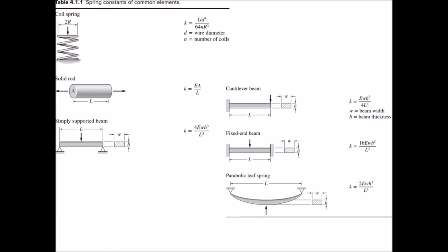So now that we've done this the longhand way, where maybe we didn't know this was readily available to us, or maybe we weren't sure how accurate a chart like this was, didn't have it in our textbook, so we went back, referenced our old mechanics of materials textbook, went through, found a beam that's fixed at both ends with a concentrated load at the center, where we could get an expression for our max deflection at the center of that beam based upon that center load, and went from there and derived our equation for K.